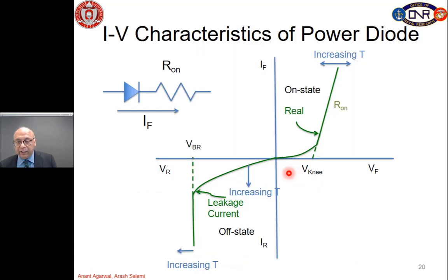So, now we get into the basic elements of diode and transistors. This one is a schematic picture of a diode, which is basically shown here as a symbol for diode, and the diode allows current to flow in one direction, in this case from left to right, and in series we show a resistance of the diode. So, the current flows through an ideal diode and through the series resistance of the diode.